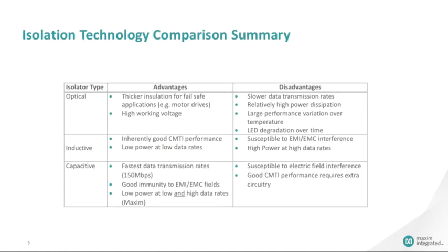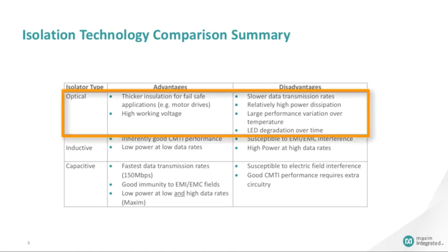Here is a summary of different isolation technologies. For optical isolators, the advantages are thicker insulation for fail-safe applications and high working voltage. The disadvantages of optical isolators are slower data transmission rates, relatively high power dissipation, large performance variation over temperature, LED degradation over time.